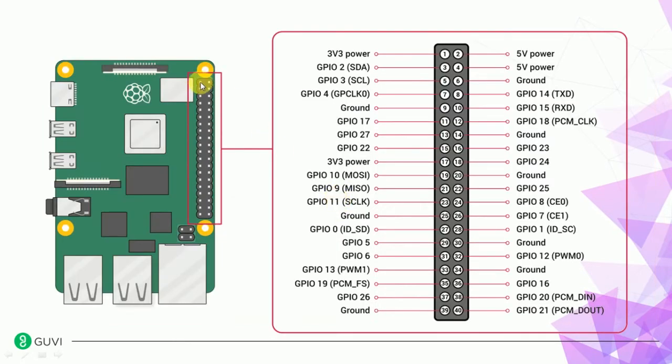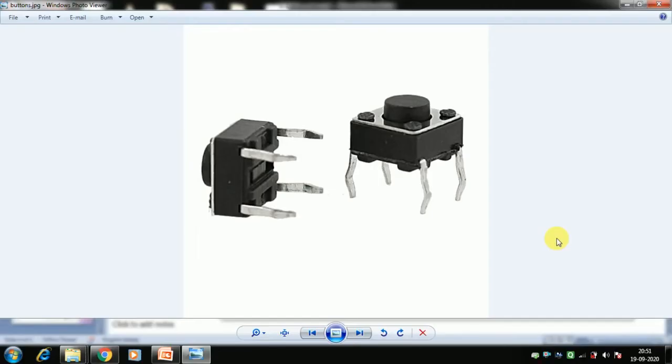So you can see beside this 3.3 volt pin there is a 5 volt pin here. Please don't use the 5 volt pin, because the GPIOs are only 3.3 volt tolerant on Raspberry Pi. If you apply 5 volt, it may damage the Raspberry Pi. But in our next video we'll see, if you have a 5 volt supply, how you can divide it through a voltage divider, and how you can still read the value by limiting your voltage within 3.3 volt.